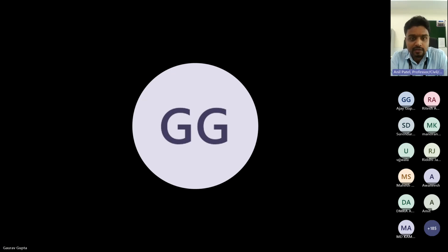Okay, Swapnil, if you want to get the Wood-Armer moment directly from the software, then you have to use the Midas Gen software. Instead, there is MX, MXY, MY. So if you want to adopt the Wood-Armer moment directly, then you have to use the Midas Gen software. STAAD Pro doesn't have this feature as of now.